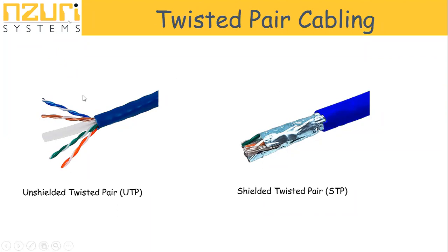Now, usually when electricity is generated through a cable, it has some magnetic fields that it cannot help generating. And in a typical example like this that you see there, if these cables are not twisted, that magnetic field generated will have an impact on the data that is sent through this cable, and it will start changing the ones and zeros. So the twist is there to help you even out the magnetic interference that it creates, right? And the plastic you see inside the category 6 cable helps separate the cables so that it gives you better EMI resistance.